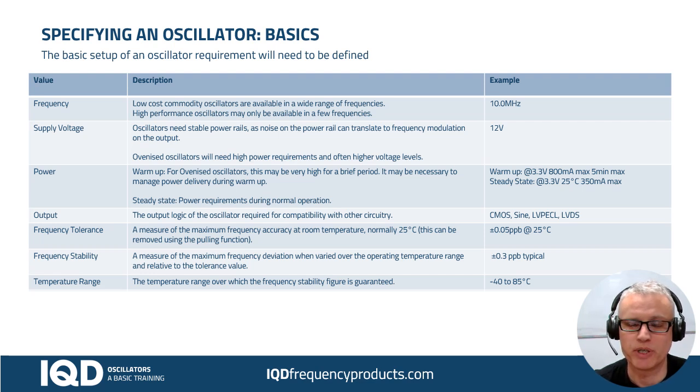it happens over temperature. So if you really don't need -40, if you're working in something like a server cabinet and you're never going to see temperatures below -10 or even +10 degrees, and you're never going to see temperatures above 70 or 80 degrees, then that's a much reduced temperature range for us to control behavior over, and that's going to make the product easier for us to design. So that is going to have an effect on the cost for the product.